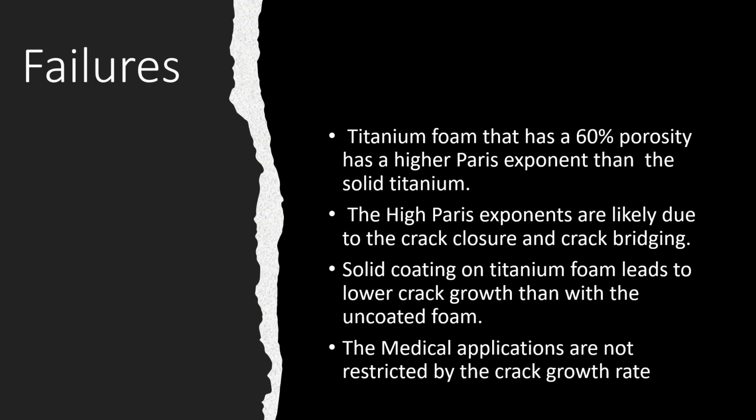Finally, when researching titanium foam, I came across a study that tested the failures of titanium foam. Some of these findings can be seen to the right, which include titanium foam that has a 60% porosity has a higher Paris exponent than the solid titanium. The high Paris exponents are likely due to the crack closure and crack bridging. The solid coating on titanium foam leads to lower crack growth than with the uncoated foam. And lastly, the medical applications are not restricted by the crack growth rate.